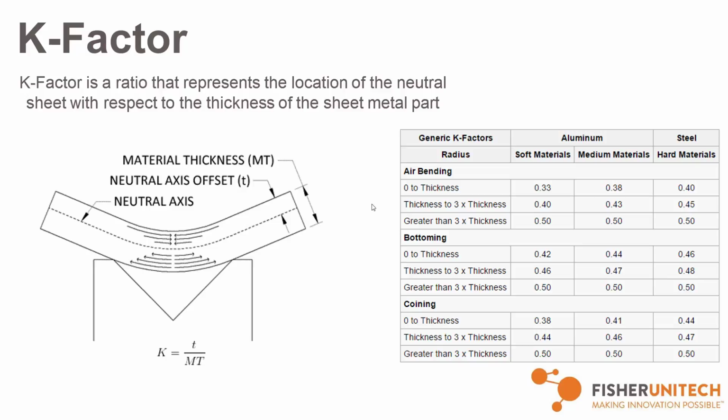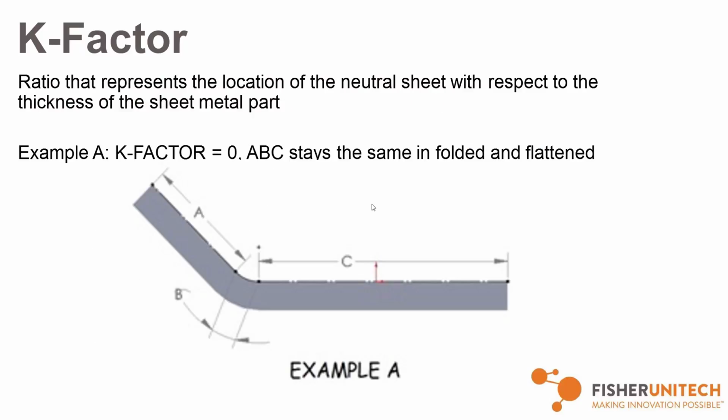I just mean that across the board when you're changing materials, you don't have to change the K factor for a different kind of material. Aluminum, once you get above 1/4 inch or 3/8, stretches a little bit more. But that's what I meant. Okay, thanks.